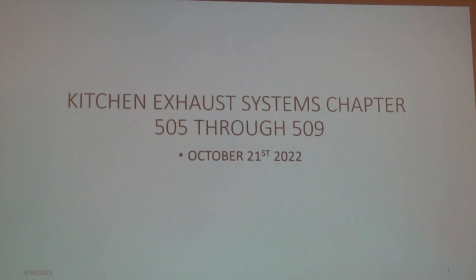So that is a major change. And also they solidified the language concerning recirculating hoods or vent-free hoods. Even though they think they're out of the woods, they still have to provide some sort of ventilation exhaust system according to Chapter 4, and we'll talk about that.